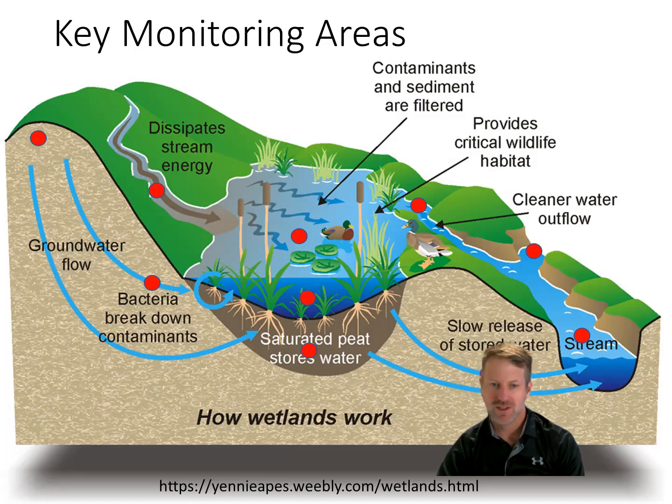to a stream. So these are opportunities for us to install sensors to understand, again, how much groundwater may be interacting with the site. We can monitor water level in small wells drilled into the bank of the wetland. So these are typically also points where people would be going out to collect macroinvertebrate surveys or other data, whether it's looking for the presence of, how wet is the system, how deep is the water.